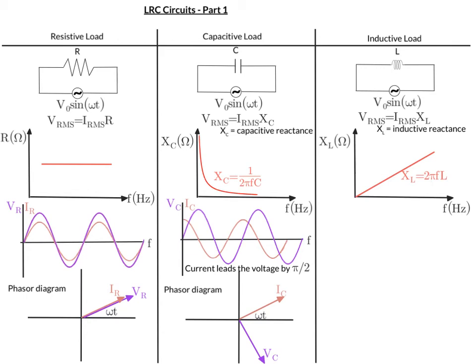So let's think about how inductors behave. If current goes through here, then the inductor all of a sudden experiences a current, which means that it's going to produce a magnetic field to oppose that current. Now, if the direction of the current is the same for quite a while, the inductor does get a chance to get used to that direction of the current, and it doesn't react very much. So when the frequency is low, then the inductive reactance is also low.